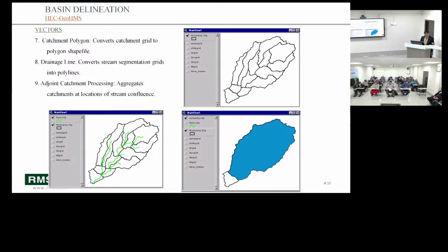So you can use those catchments to put in that information, and there is a provision to put one single parameter for one single subcatchment. There is a provision to increase or decrease the level of those subcatchments. If you increase the threshold, your subcatchments will be reduced, say 5 or 4 subcatchments.